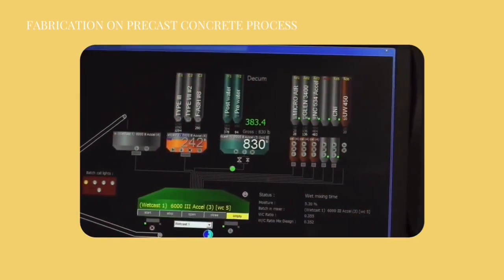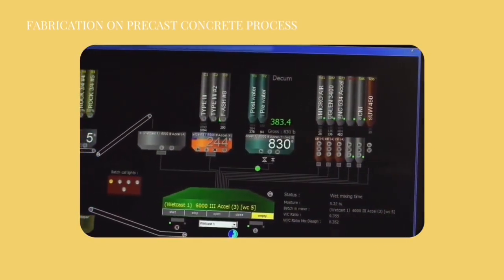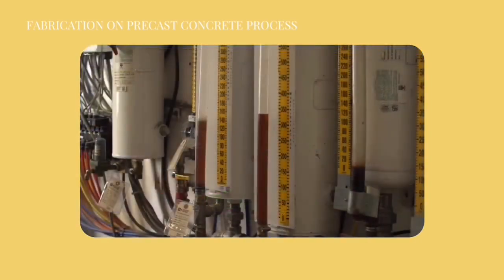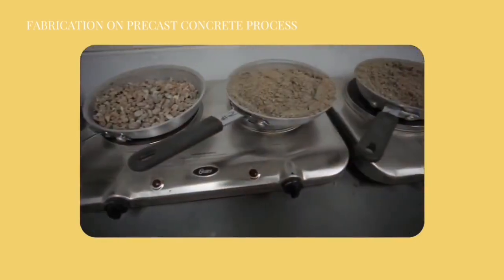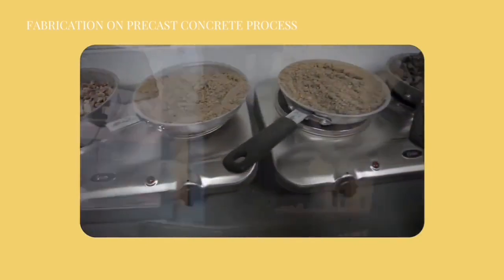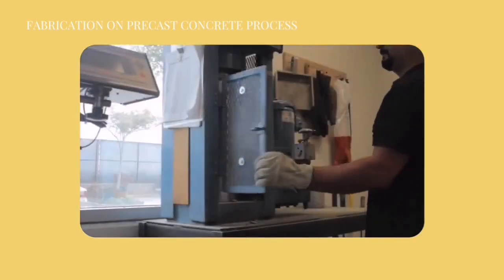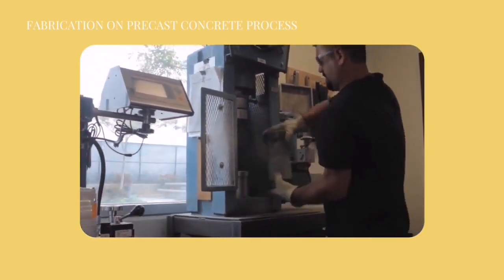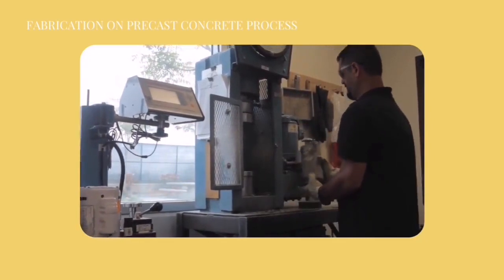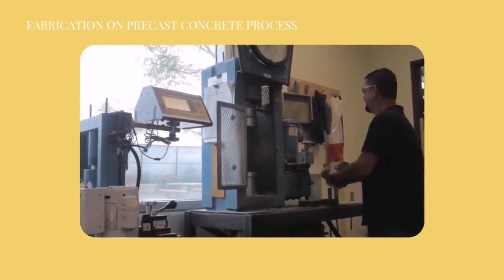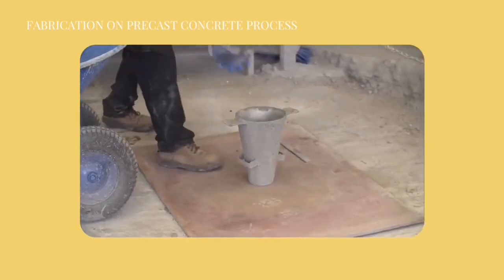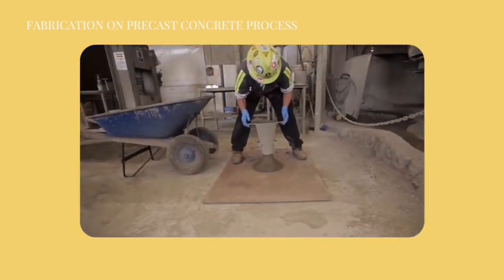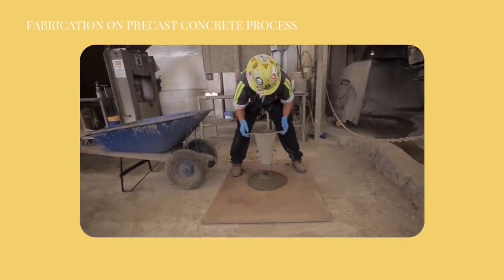Each Oldcastle Infrastructure precast factory has a concrete laboratory used to conduct routine raw material testing and control exact quantities for each batch. This is especially important when using high-flow self-consolidating concrete. The lab collects sample cylinders used to check compression strength and verify quality of each batch. Once the materials are properly mixed, the self-consolidating concrete undergoes a variety of additional tests, including a spread test to verify the mix has the proper flow and no segregation of the aggregate.